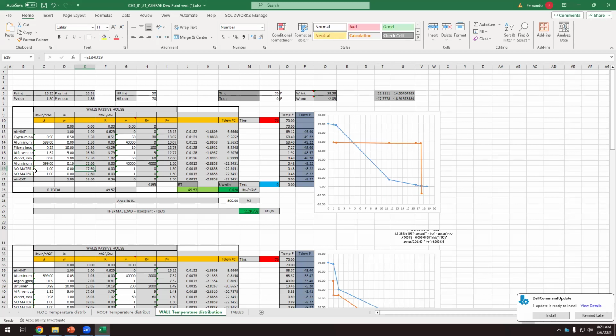If you have the exterior siding and the interior finish, you place it inside out. But what if you receive just the wall and then you apply the siding on site? It's very easy to wonder, is it inside out or outside? I don't know. I place it the other way around and it will have this effect. So we have no condensation risk because we have placed the vapor retarder in the right position.